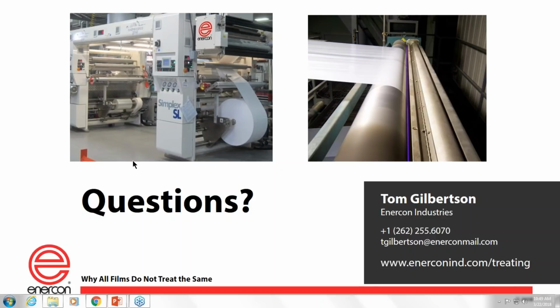What are the parameters to ensure a good maintenance of the treater? Well, really, it's just, again, like a lot of things, it's just paying attention. Just visual inspection. You should be visually inspecting that corona treater, and the areas of visual inspection that are required most are surrounding the electrode. Without respect to the type of electrode, whether it's a metal electrode, segmented or fixed, or whether it's ceramic electrode, it doesn't matter. This all applies. Inspect the electrode. Make sure there's no dirt, debris, carbonized film, anything like that. Make sure none of that stuff is on the electrode. If you see some on there, clean it off.